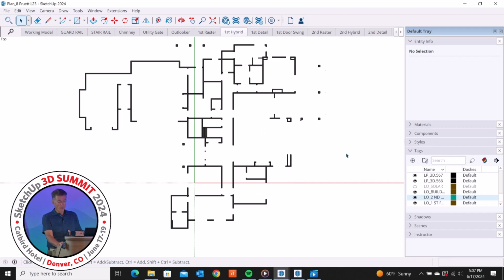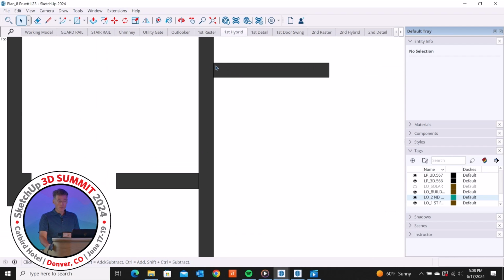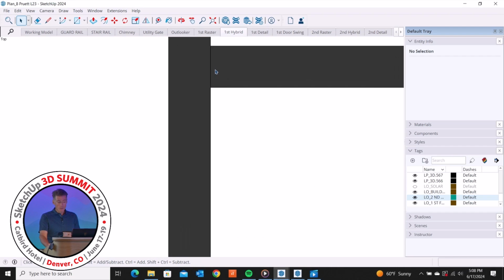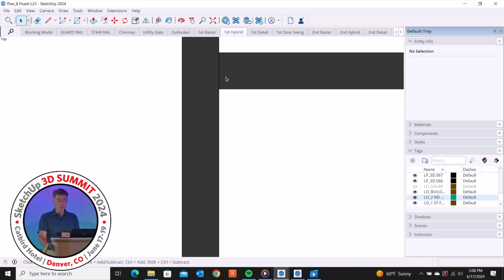So what that does is when we do a section cut, the only thing that appears is what's at the section plane. And then we establish what that section color is. It's wonderful because you're not creating line work like I used to do, because even if you set this to a gray, or this one's really dark, there will be like a little outline that it creates. I go pretty dark because sometimes you get this. You can see that little line. And I don't necessarily want that to read on the plan.